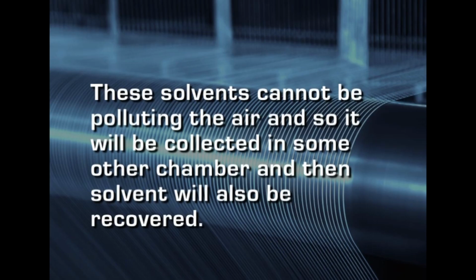In this process, about 10% of the solvent may be lost or may be present in the fiber itself. But it is considered to be a costly process, because whatever solvents are used here are all very costly and maybe inflammable, and sometimes toxic also. So, these solvents cannot be allowed to pollute the air, and they will be collected in some other chamber, and then the solvent will be recovered and used again for the manufacture of these materials.